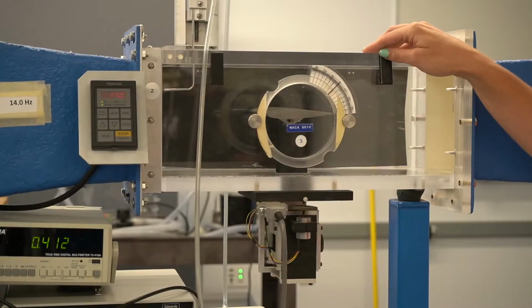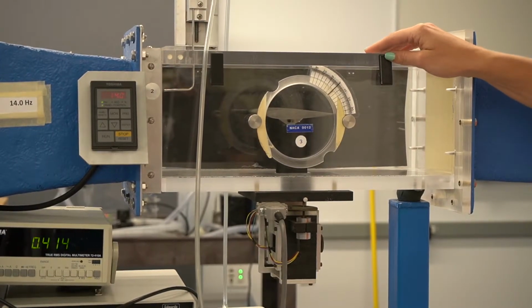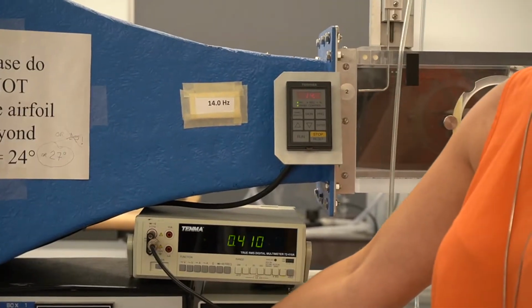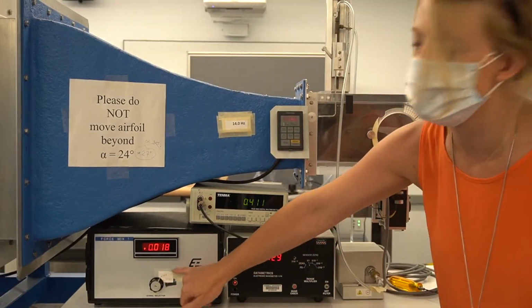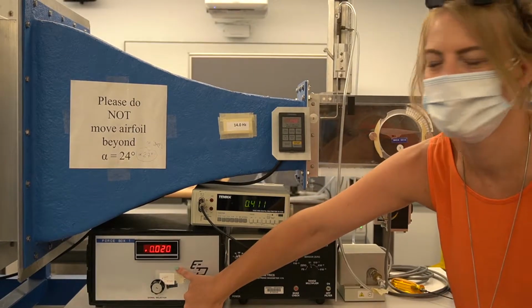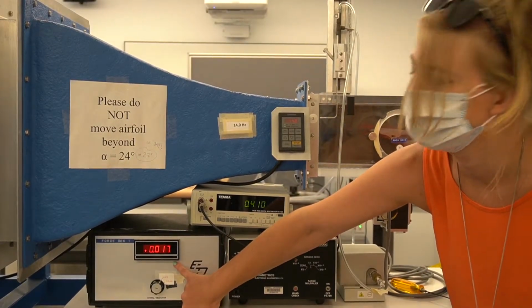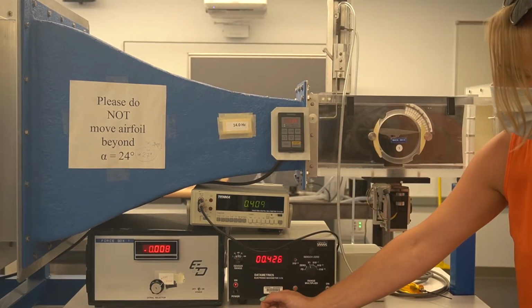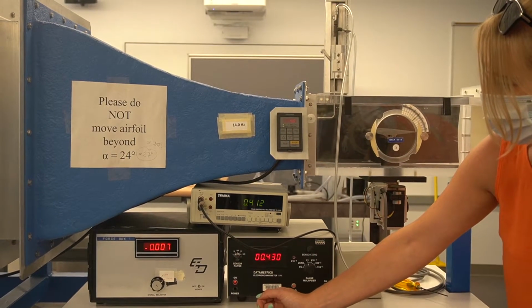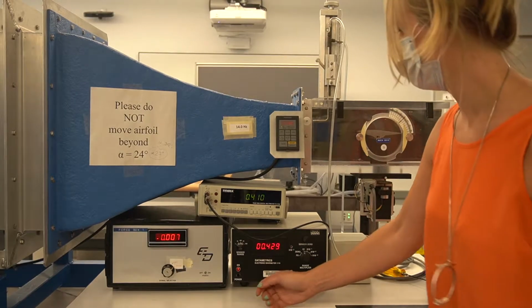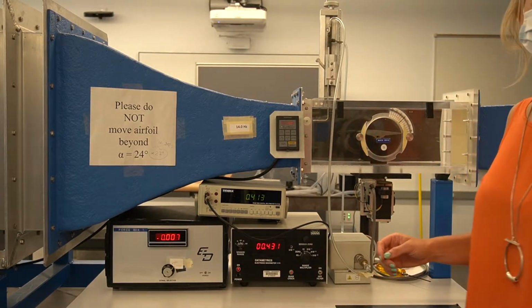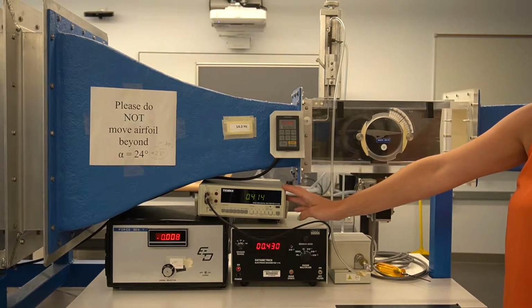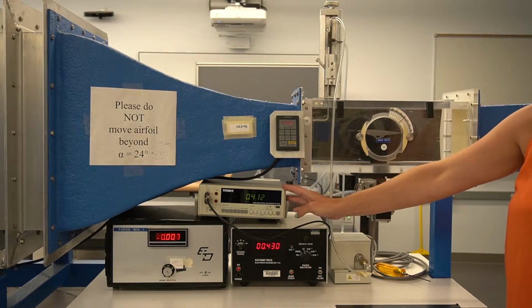So we're going to start with our NACA 0012 airfoil at 0 degrees. And we're going to be measuring, firstly, the lift in volts, which, Jay, what is it? Right now, it's 0.02. And the drag? Which is very close to 0. It's 0.008. And our PT minus PS, we measure up the top here, which is 0.412.